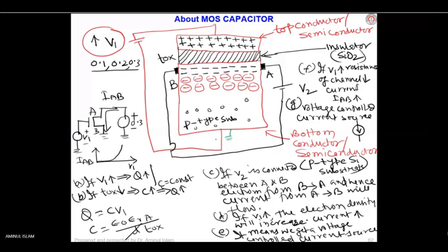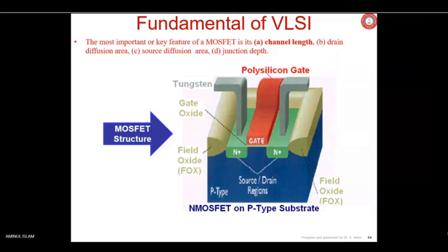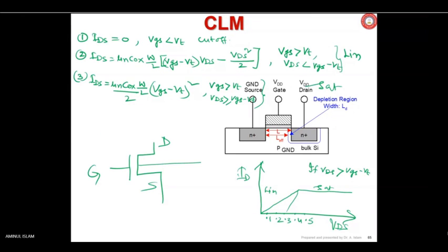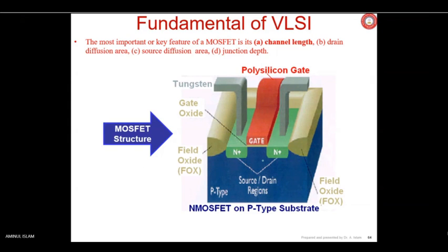Okay, but in the next slide I have shown that it should be connected from the top. So as can be shown here, you see the same thing shown in a three-dimensional view. This whole blue portion is a kind of brick, and we are seeing the front view from the front side. That is your body or substrate, the p-type substrate, on which the n plus green region is made by ion implantation.